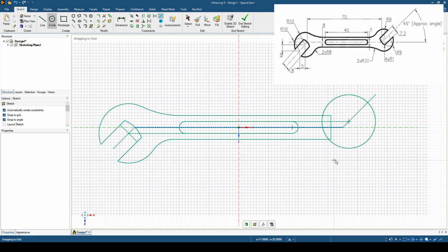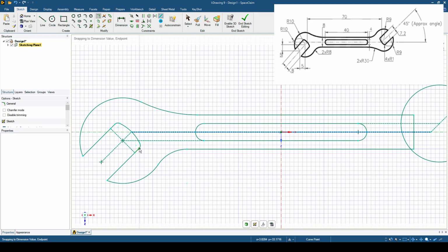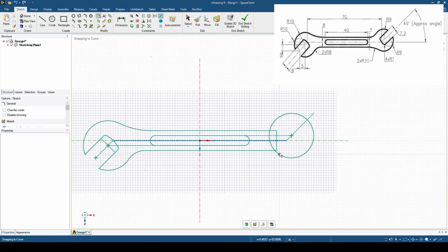And now, in order to do the same as we did before on the other side, we have actually, as it said, a radius of 1mm on each side. So we did miss this actually. So I go back to create rounded corner, and I should have from there to there 1. And from there to there 1. So it looks better right now. The same should be on the other side, but for now we finished this side first.